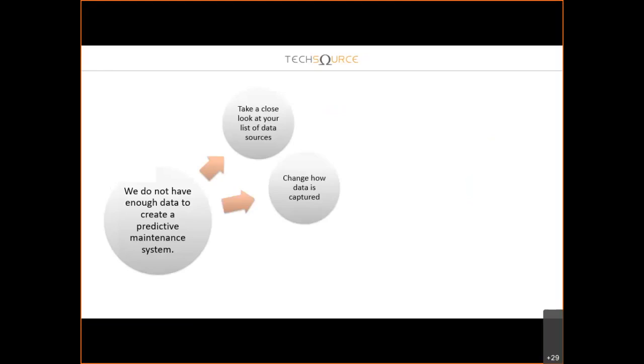Next, you might change how the data is captured. Some systems operate in a break-fix mode where little to no data is collected until a fault occurs. Others only log event codes and timestamps, so engineers are notified that the event occurred, but not the sensor values at the time of the failure. Although this data may be useful for diagnostics, it is unlikely to be sufficient for developing a model that can predict the failure. So consider changing the data logging options to record more data, perhaps on a test bed if production data is not available. Depending on the load on existing embedded devices, it may be possible to reconfigure them to collect and transmit sensor data. Or an external data logger may be necessary to get started.